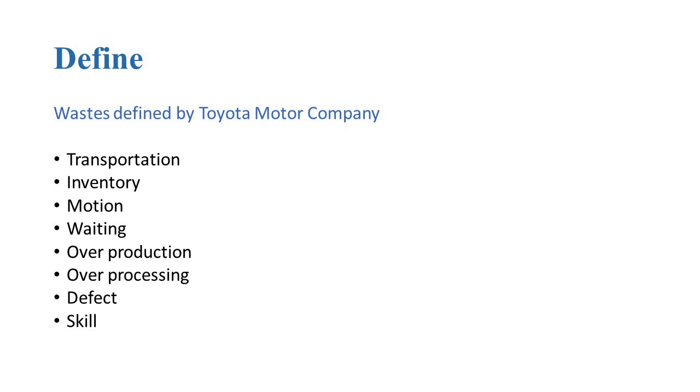The main objective of the Define step in DMAIC is to identify the opportunities for improvement and make the project more efficient. In our project, the customer demand is producing 6,000 parts in an available time of 40 hours, and per hour demand, this can be achieved in 38.96 hours. But in the practical execution, we found that 1 in 5 products produced is defective. So the waste in our project is mainly due to defective parts and idle time. The high defective rate in the initial design is addressed by redesigning the product, which is shown in the further slides.